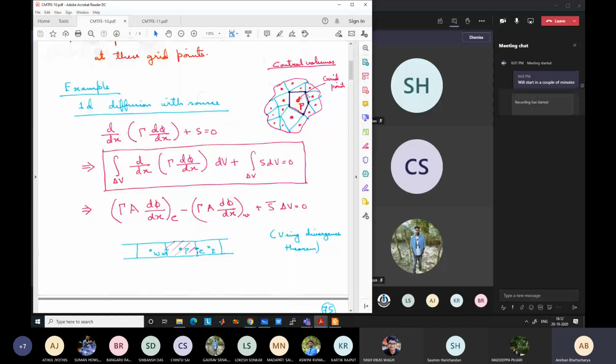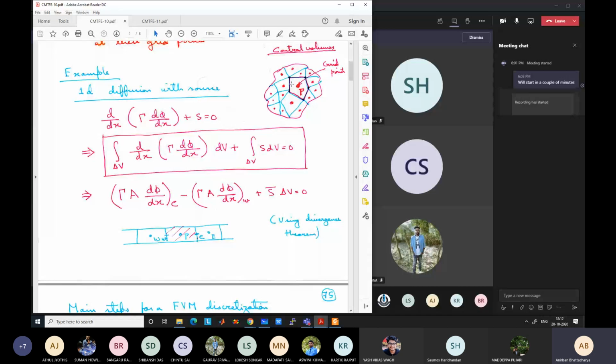And because of the nature of this derivation, all the properties such as heat flux, mass flux, and momentum are conserved over each control volume and, as a result, over the entire domain. This is a very important property of finite volume, and it is valid even if the number of grid points or control volumes is very low. Say if I divide the domain into only 4 control volumes, the conservation will still be there. We don't have to check for conservation. The mass and momentum will all be conserved over the entire domain.